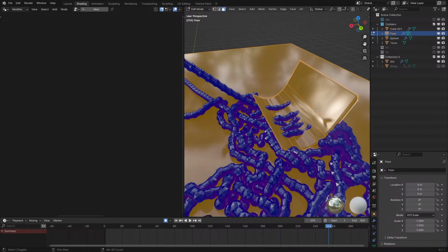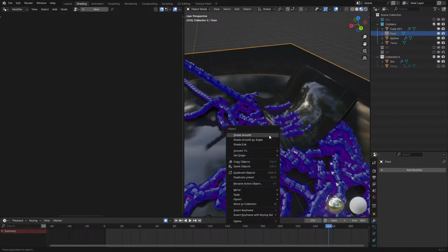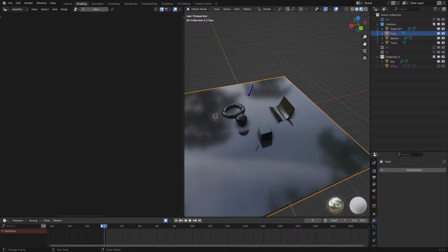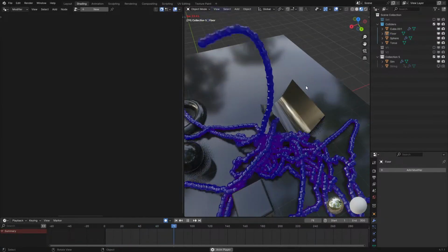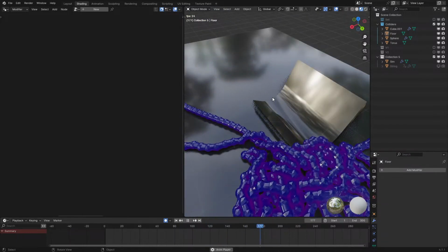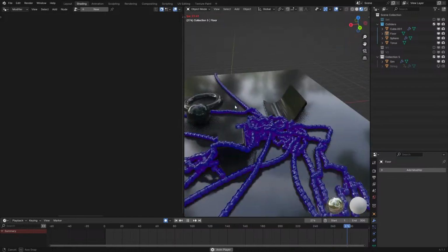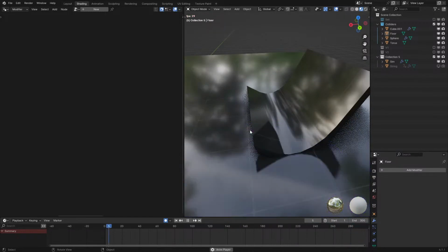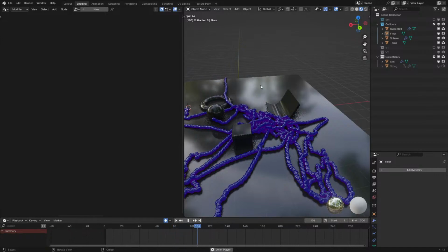Let's go and recalculate normals. And also, yeah, let's turn off the bevel. And then shade smooth my angle. Yeah, that's good enough for me. There we go. So now we have that, and it seems like that's working a lot better. No severe jittering. There's a little bit, but again, these are only referencing one of their neighbors, which will always cause jittering, so I do need to figure out spatial hashing.